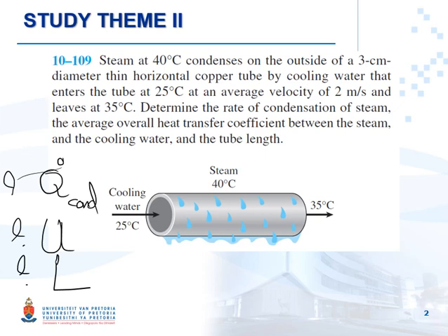It looks like a very standard condensation question: find the T_sat, immediately read h_fg and rho at T_sat, read the rest of the properties at film temperature, find h_fg star, and after that find the right correlation for h and you will be sorted. No. It's a trap.